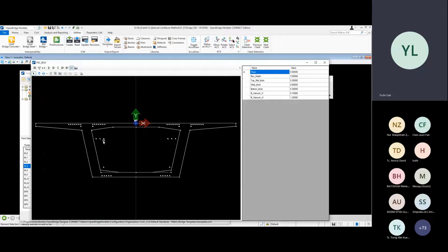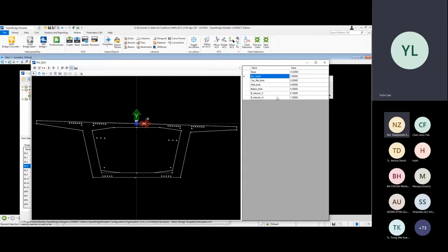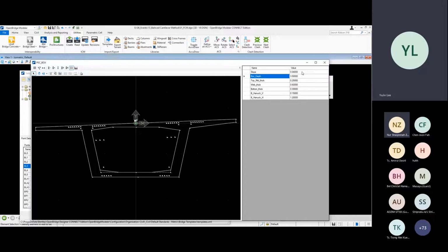Move to the verify button and modify the super elevation and each variable along with these sections. Then you can see the adjusted tangent point by these variables.